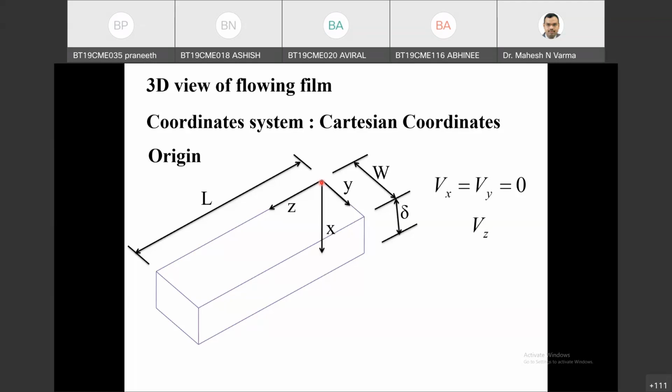Fully developed flow you are not telling actually. So I am asking if the velocity here and the velocity here is the same or different. So it is constant for fully developed flow plus steady state plus one direction. It is not given that it is 1D flow. We are assuming 1D flow. Okay, sir, even if we are not assuming it to be 1D flow, even then it is correct. I'm telling you are correct, but all the logic you are giving is wrong.